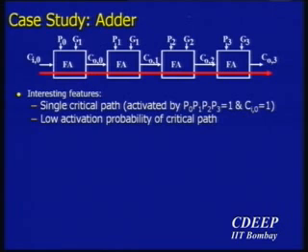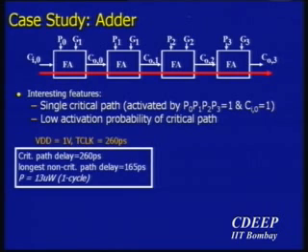So that's exactly what was done right here. If you look at this ripple carry adder, it's a very simple example of a ripple carry adder. The critical path delay for a 1-volt operation turns out to be 250 picoseconds, 260 picoseconds, and that's the clock cycle that we use for this operation. It turns out the power consumption was about 13 microwatts.